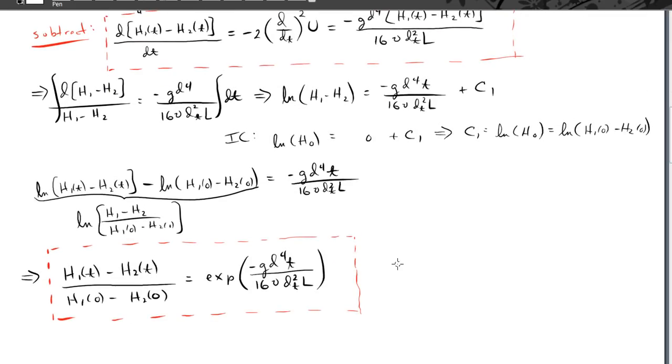Now we've obviously made some approximations. We've neglected the viscous losses at the inlet and outlet of the pipe, the contraction and the expansion. That would alter this result somewhat. You wouldn't have as nice of a formula like this. You might actually have to integrate the resulting equation numerically. But this is a very good approximation within the constraints we're given for the problem.